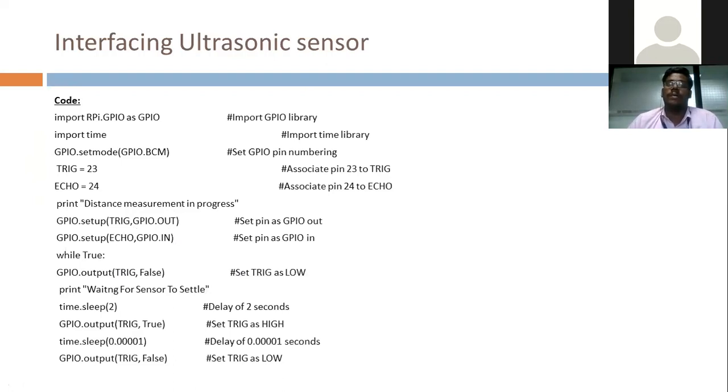Raspberry Pi sends a pulse via ultrasonic to the outside environment. So we are generating the pulse inside our coding. We are generating a pulse from one full cycle, one positive cycle and one negative cycle, for 10 microseconds. For that purpose, we are using GPIO.output with the pin and a value. The value is False, and False means 0.